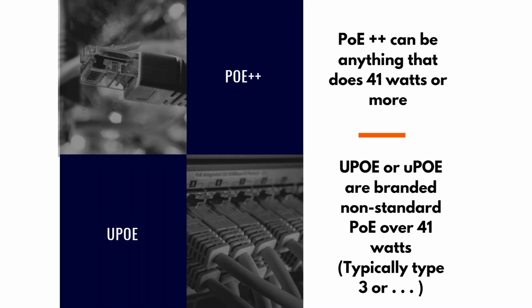So with all of that context, we can finally answer the question: what is PoE++ and UPoE? PoE++ can be any type of PoE greater than 41 watts. That can be type 3 or type 4, and any class you want within that. For more details, ask to get the specifications on whether it's 802.3 BT, what type it is, and what class it is. If you can't get it because it's not on the spec sheet or the person you're talking to doesn't know, at this point you can typically assume it's type 3 class 6. It's the safe bet.